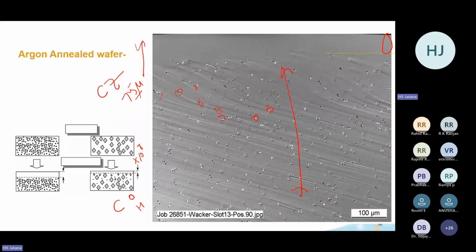But the first step is an annealing step. You can see this. After annealing, I have pushed these impurities, which were at the top, down. There are various annealing techniques, known as gettering, which you might have studied, backside and front side gettering. So I have made this area purely clean. There is no impurity. It is a very small area, 4 to 5 micron, and all other impurities have been shifted. I will do the processing in this area, and after the wafer is tested, the wafer